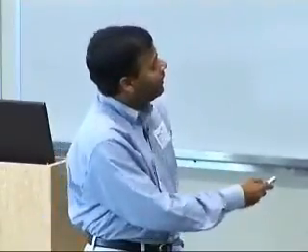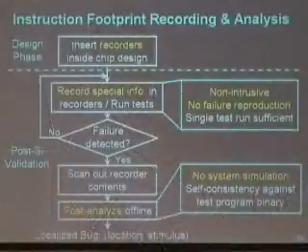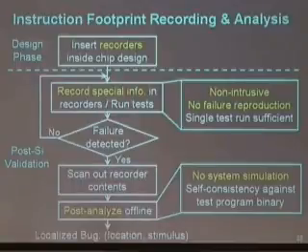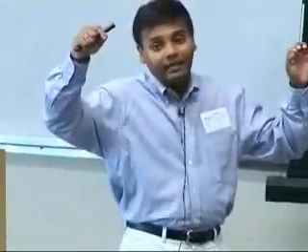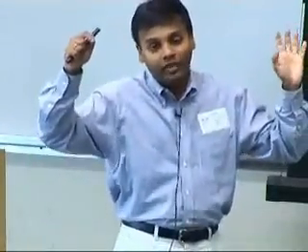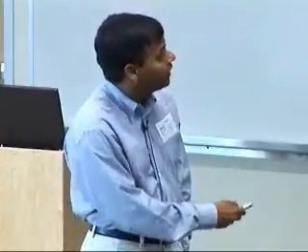And when post-silicon validation is happening, these recorders store special information in a non-intrusive way, because you do not stop the system or anything. It's all happening in parallel. And when a failure is detected, that's what is important, because you want to detect the failure fast. If the error appeared a billion cycles from the beginning of your validation execution, you don't care about that. What you care about is the time from the appearance of the error to the appearance of the failure. You want that to be very short, and that's where some of the error checking techniques play a very special role.